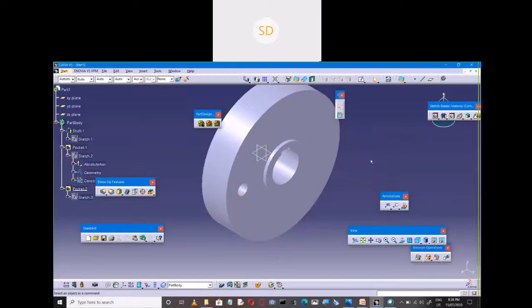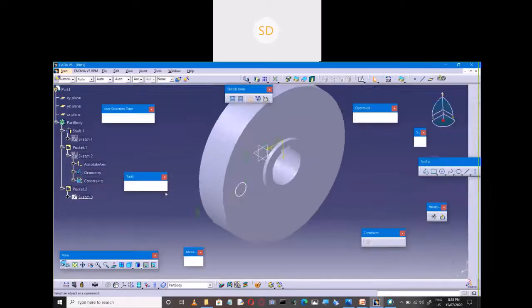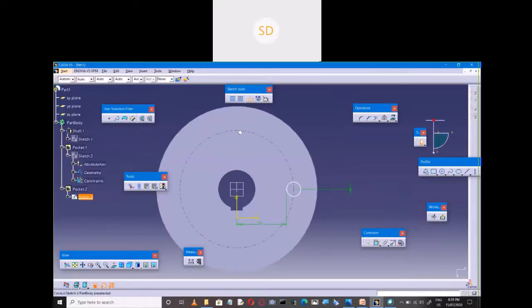Okay. So as you're performing a cut operation here, you can draw 4 holes at a time. Instead of drawing one hole, you can draw 4 circles at a time and make a cut. Otherwise, according to the manufacturing process, you need to go for a hole operation that has to be carried out by drilling. Right.